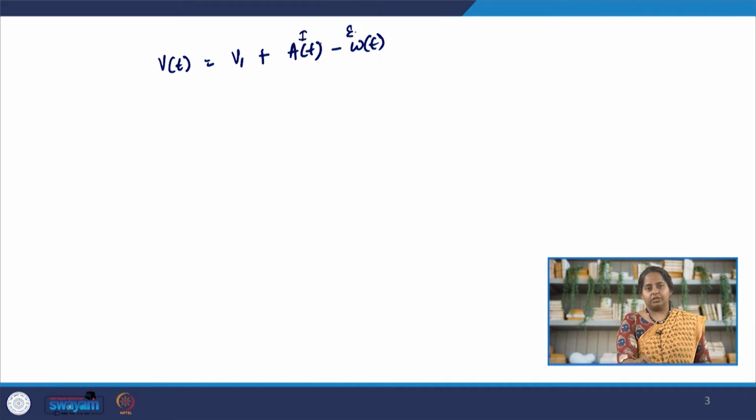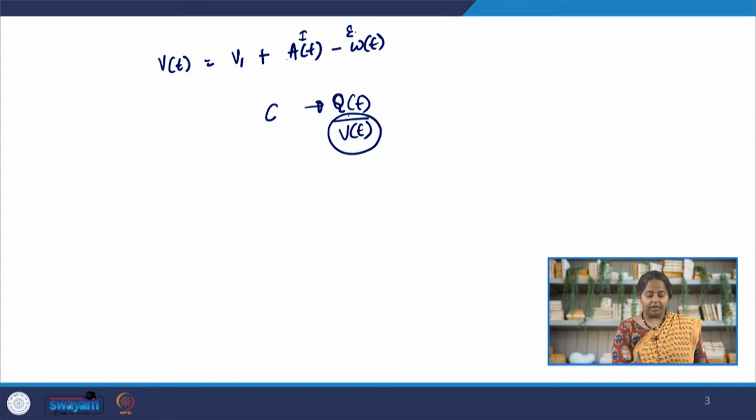How is this going to change the concentration of bacteria and antibiotics in the slurry tank? Since the volume is changing, remember concentration. To find the concentration, we need to account for both the flow rate, the rate at which a contaminant is coming in, and the rate at which the volume of the tank is changing. Both need to be accounted for to find the concentration of any antibiotic, antimicrobial, or bacteria, whether resistant or sensitive, inside the slurry tank. Now here, Q is changing, V is changing, both are changing with time. So, both need to be accounted for.